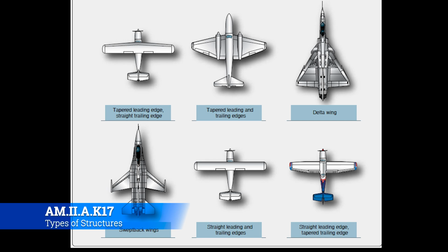There's a couple of them that we're going to talk about here. That's just a rectangular wing. Now rectangular wings are really good for going low and slow, and that's what that type of aircraft is going to be doing. It's not a high performance aircraft. It's going to be built for economical lift production and stability, and that's really kind of all there is to it.